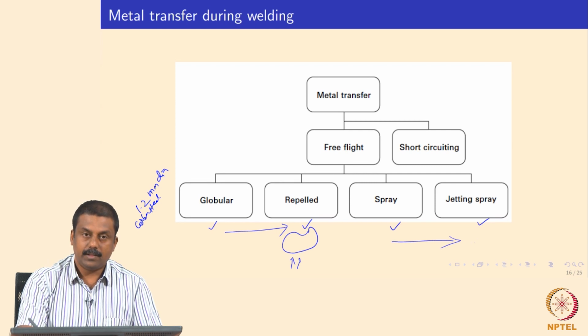You will end up having spray velocity increase compared to the conventional spray mode, and you will start having a stream of molten droplets continuously transferring. In this mode it is not generally advisable because, with increasing Lorentz forces, you may have a local disturbance in the transfer, so you may also end up having spatter because of these increasing Lorentz forces.